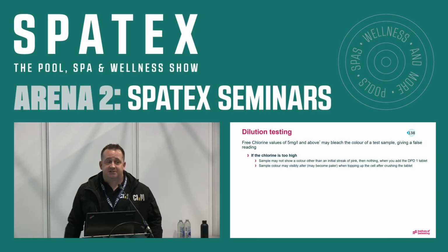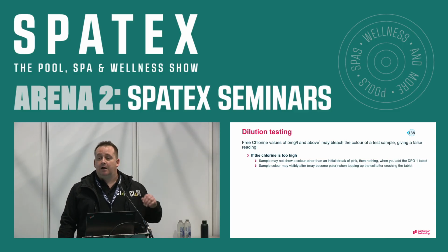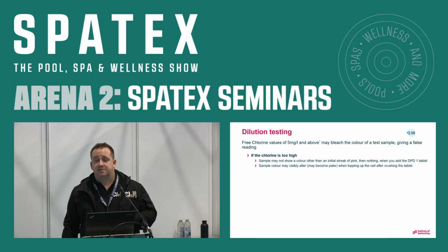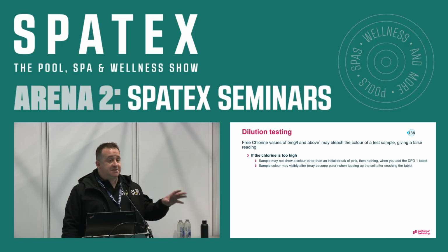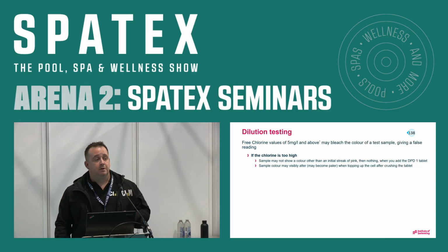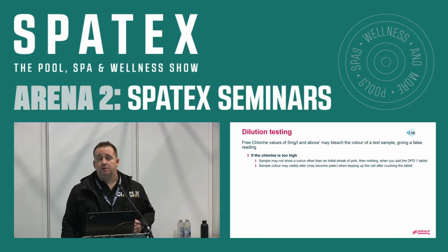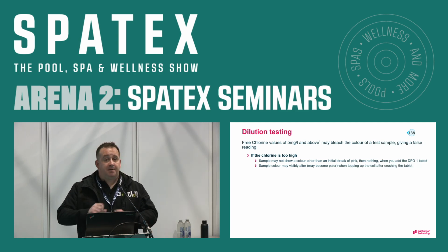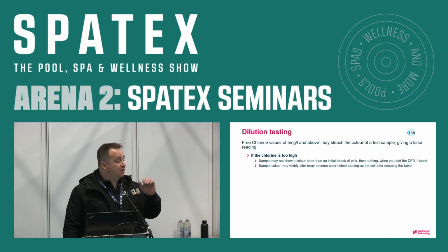Okay, dilution testing. This is a nice little tool to have in your back pocket, okay, to get yourself out of trouble in case you have an issue. All right, on your sites, if your dosing control unit has a hissy fit overnight and decides to empty the contents of the day tank into the swimming pool, yeah, you won't know about it. You won't see it in the pool, okay, until you put your DBD1 tablet in, you crush it up, and it gets bleached out, so you don't get the pink colour. You need to dilute your test solution so you can get an accurate reading.